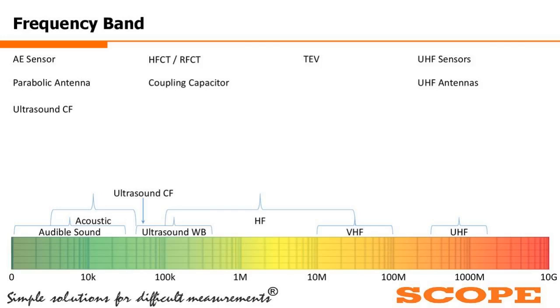The frequency ranges that I'm telling you are again in line with the recommendation, or the idea of the manufacturer, that the probability of occurrence of partial discharges in these frequency ranges is maximum. These are again not hard and fast, but if you are working in these frequency ranges, you are playing quite safe to detect partial discharges, right? The probability of detecting those signals gets higher. So in UHF, our frequency range is from 200 megahertz to 1500 megahertz. So it is a radio frequency kind of range.